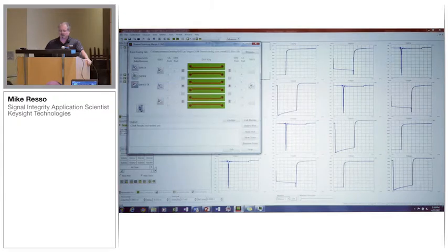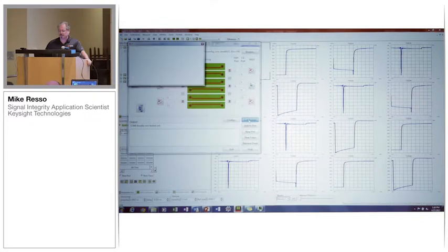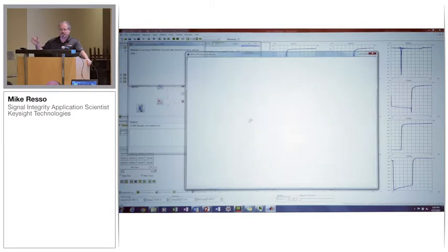And I'm going to generate FEXT and NEXT like this. So now I've basically got the configuration, I've got my crosstalk aggressors, and now all I need to do is call the MATLAB routine. So I press this button that says call MATLAB, and so it's going to call MATLAB in the background. This is a DLL, so you don't need the MATLAB license.